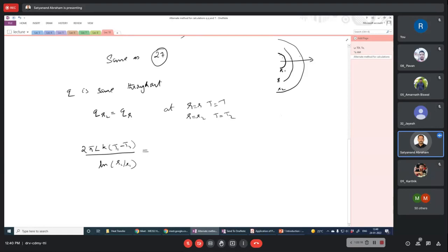Here we consider the full wall length, so the wall resistance and the full temperature potential are assumed. If you assume only a partial length, or some other radius R, then we have to find only that potential and that resistance. Then you get 2 pi L k (T1 minus T) divided by ln(R by R1). Yeah, so now you can do everything.